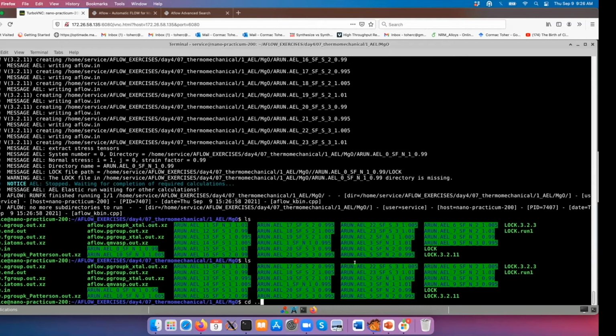So being able to turn off this strain symmetry option can be quite useful if you want to check for things like errors. Because the 3 different directions should be the same, you can actually see just how much numerical noise you're actually getting in your calculations.